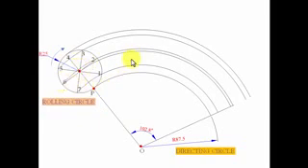Arcs have been made from all these points, and the next thing to do is, when this circle starts to roll and completes its one revolution, you should realize all these points are going to make an impression over here. Like point 1 is going to make an impression here, point 2 is going to make an impression here, 3, 4, 5, 6, 7, and finally P. So you should realize that this arc over here will get divided into 8 equal parts, and that's exactly what we're going to be doing right now.